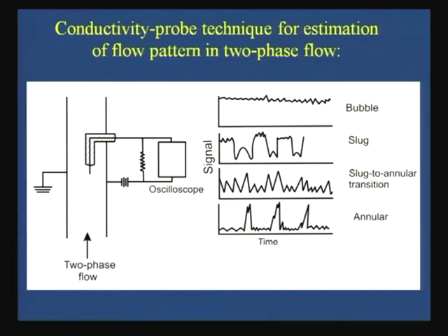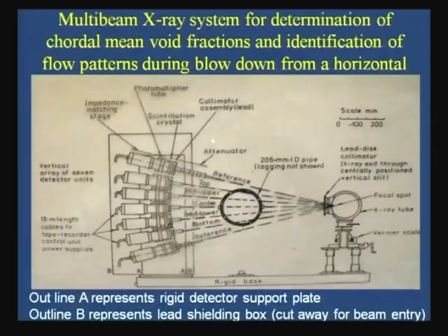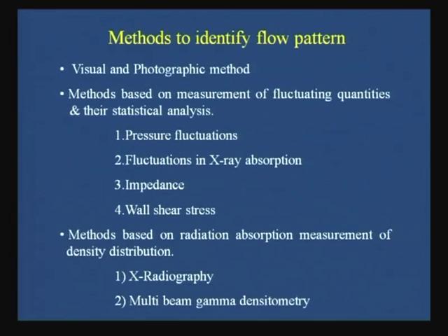There is another technique, which is by measurement of the pressure drop signals. Now, there are a number of things that we can measure. First, we can simply measure the pressure drop as a function of velocity. We keep on increasing one velocity, keeping the other constant, and then we measure the pressure drops under different circumstances.